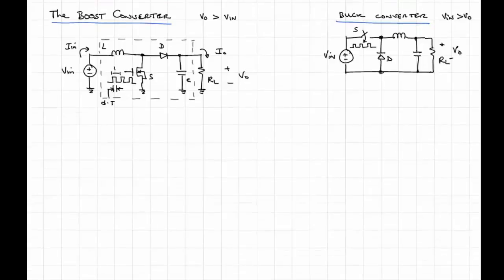Okay, so here's the boost converter, what the circuit looks like, and you will in lab be building something very much like this. It really is nothing more, at least in principle, than an inductor, a switch, which here we're representing as a MOSFET transistor. That's a typical device that would be used because we switch this very quickly, and then a diode. Those are the three main elements. And then fourthly we have to include a capacitor, which is storing charge for us. So an inductor, a capacitor, a switch, and a diode. And that comprises the basic power stage of a boost converter.